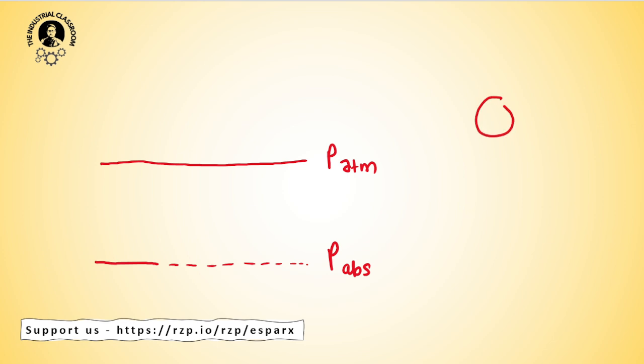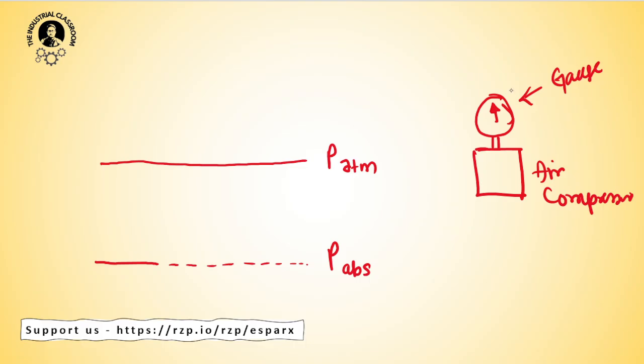Whenever you are measuring some pressure, we have a pressure gauge in it, for any industrial line. Let us consider an air compressor. We have a pressure gauge here. This is the gauge which detects the pressure of the air content in it. Remember that the gauge pressure does not measure from absolute zero, it measures from the atmospheric pressure. So gauge pressure is somewhere above this atmospheric pressure.